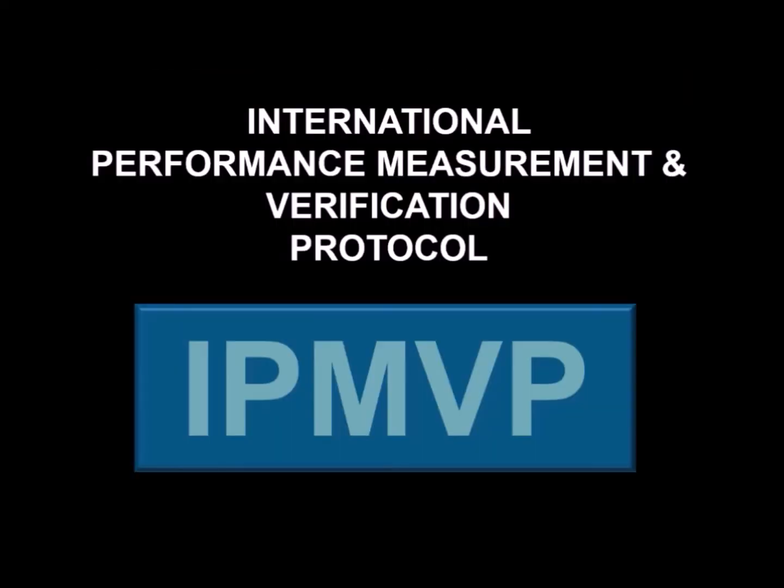Tell us how you measure the savings. The measurement and verification protocol we use is the International Performance Measurement and Verification Protocol, which is accepted in 30 different countries. It was, of course, developed in the US, and it specifies how the measurement and verification is to be done. Generally, we would look at 1 year's historical data and relate it to weather or other conditions. And then once we install the system, we will compare the consumption after installation against the consumption prior to installation for a comparable set of conditions, whether it's the same month or the same weather conditions.